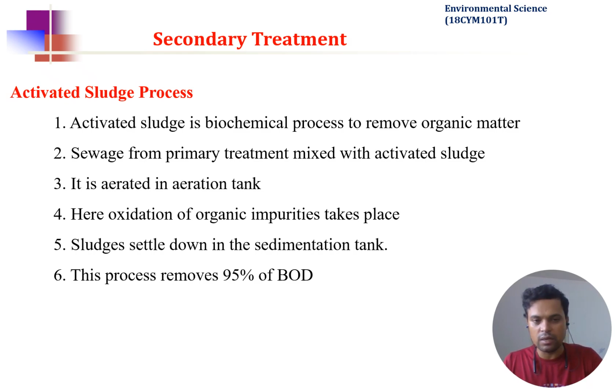Activated sludge process, which I discussed a little bit earlier. Basically, activated sludge is a biochemical process to remove organic matter. Sewage from the primary treatment is mixed with the activated sludge, which is basically nothing but bacteria. It is aerated in the aeration tank, so a lot of oxygen gas will be infused in the wastewater, because those bacteria need oxygen for survival, and they can digest that organic material. Here the oxidation of organic impurities takes place.